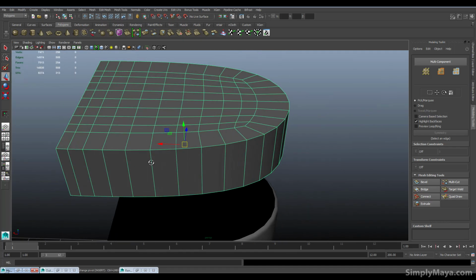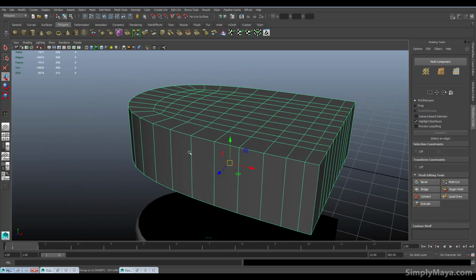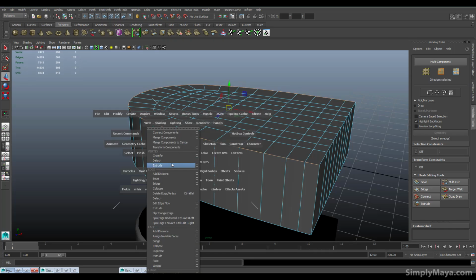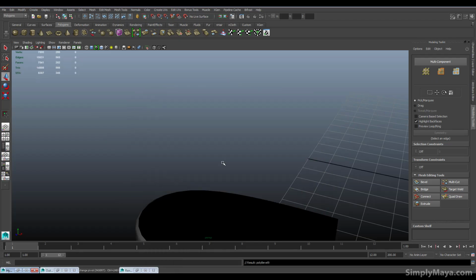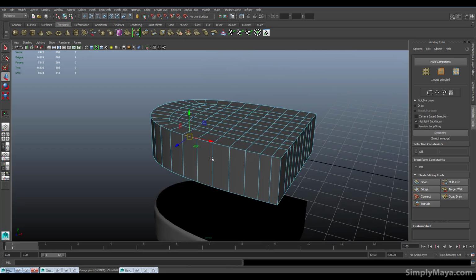We can also come in and do our own chamfers across our edges. So for instance, I can take this edge now and just go to Edit Mesh and Bevel. Okay, and that whole thing disappears. So I might have to delete the history of this.